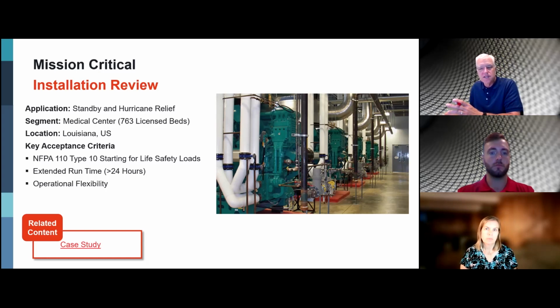to the emergency standby. Upon synchronizing to the live bus, the natural gas units will assume load of the life safety, and the diesel will drop off the live bus and start its cool down proceedings, and then return back to standby readiness. So why is natural gas an advantage?